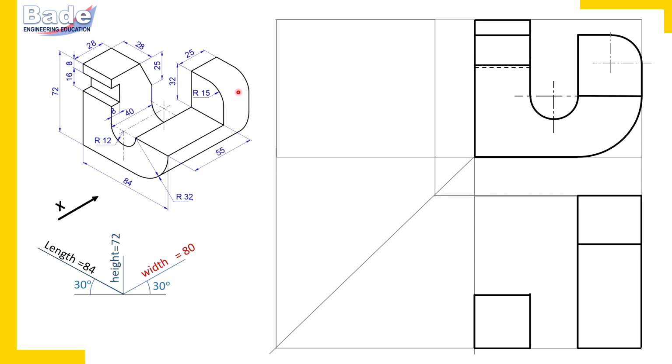The boundary of a curved surface, also called boundary generators, we make dark. Those are not edges, but boundary generators. Remember, there is a curved surface here, and this line is the boundary of that curved surface. So it can be considered as the boundary generator of this quarter cylindrical surface. Okay, so we have completed this surface in the top view.